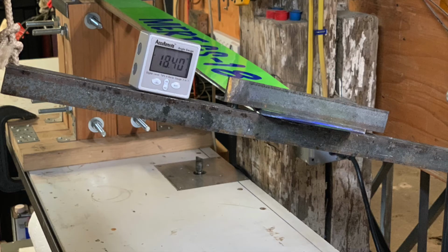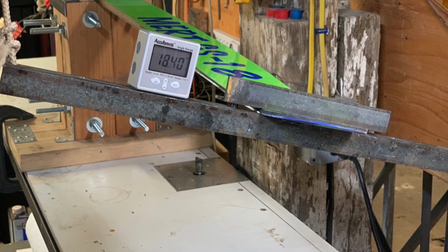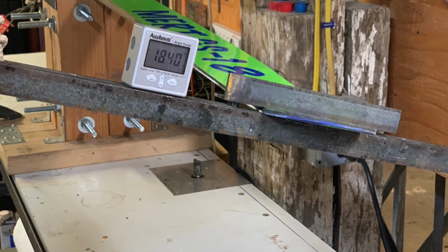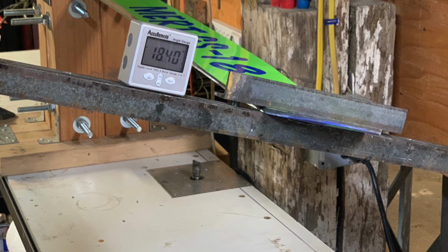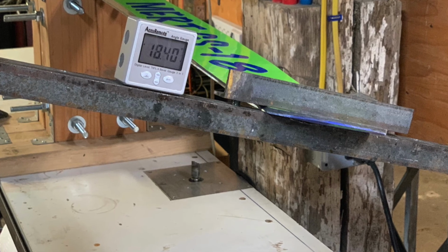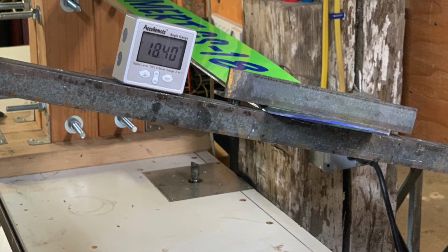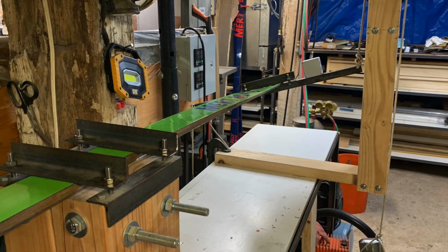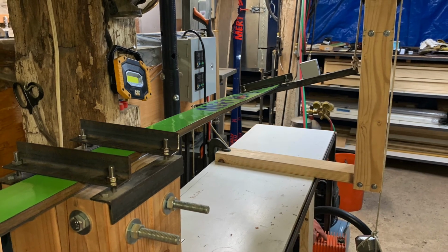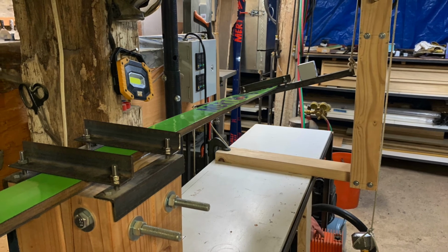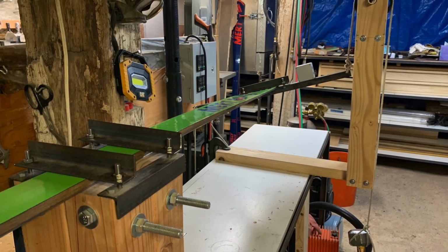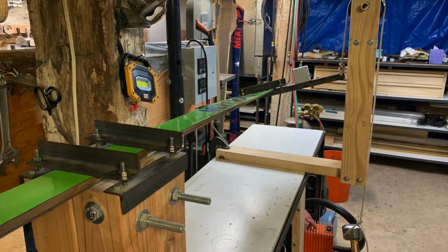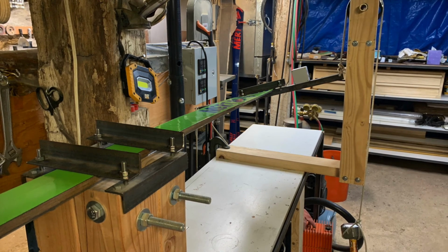How do you judge torsional rigidity in the ski shop? The answer is you probably can't. It's not as simple as bending a ski to judge its stiffness. At Mert Skis, we have a fixture we use to hold a ski at its waist and apply torque to either the tip or the tail. We then measure angular deflection. Most ski shops will not have this equipment. The best way for you to judge torsional rigidity is to get out on the slopes and experiment.